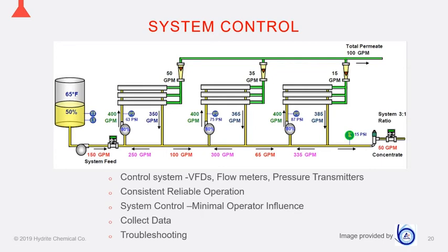And you will see a drop in permeation rate on the second stage because our solids going in is higher, 7.5% versus 5% going into the first one. And if you remember, we talked about osmotic pressure, which is that driving force to push the molecules through. We talked about if we were on a cruise and we had an RO system, a reverse osmosis system, taking in the seawater, turning it into drinking water and water for showers. And I think we said that they were for Carl's cocktail as well. He wants some ice there in his margarita.